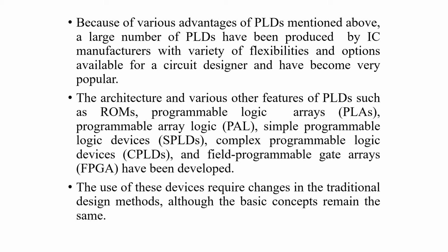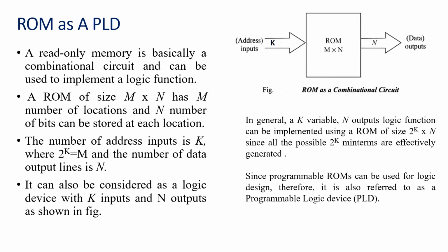The use of these devices requires changes in the traditional design methods, although the basic concepts remain the same. In general, a k variable, n output logic function can be implemented using a ROM of size 2^k x n, where 2^k is equivalent to m.